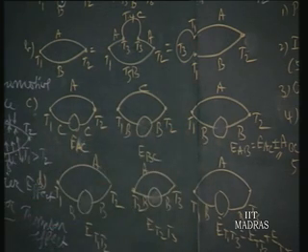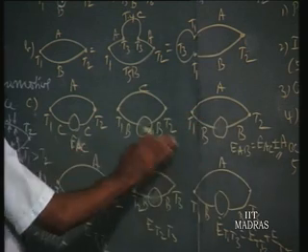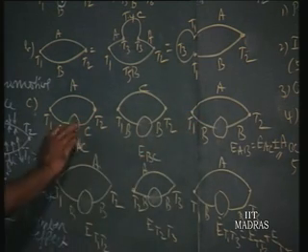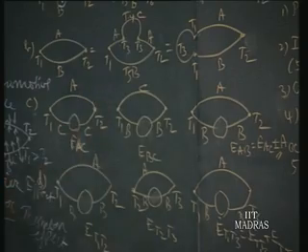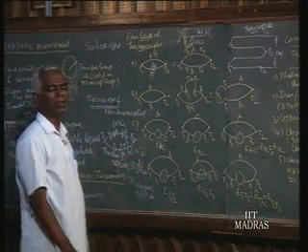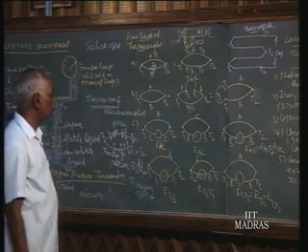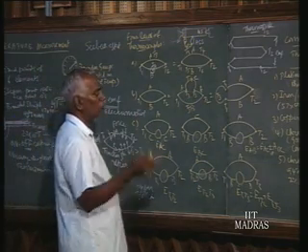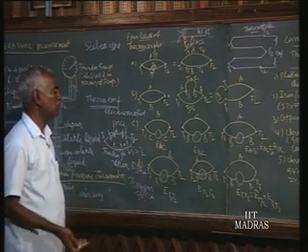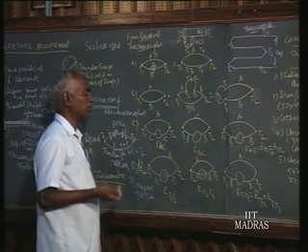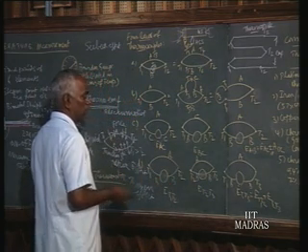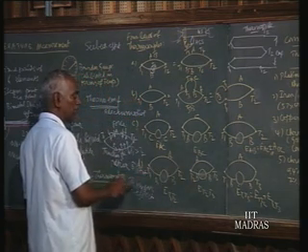Once you check for one reading, later you need not do the calibration; simply obtain the calibration curve for other points from these two standard charts. So the calibration procedure is made simple by the third law. The fourth law states the cold junction temperature need not always be 0 degree centigrade, it can be any other temperature, preferably the atmospheric temperature. So that is explained like this.